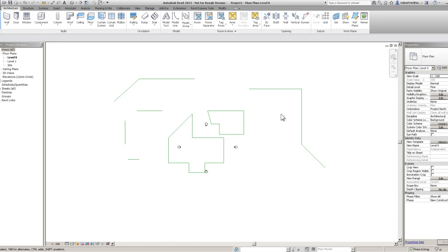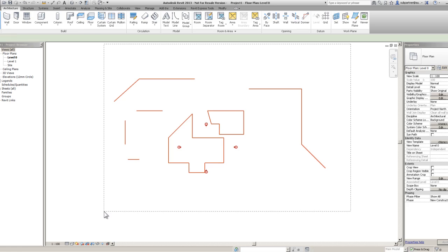This time I'm going to go from right to left, and again I'm going to left click and hold and drag my mouse. You see this time it looks like a slightly different window, again similar to AutoCAD. Remember, after showing you all this stuff, AutoCAD is a swear word, but I will keep referring back to it just for now, to help you in this transitional phase. As you can see, the window is a dashed one, and as you've probably guessed, the dashed one will highlight or soft select anything that it touches. It's more aggressive, it's quite nice. I quite often do it when I want to select everything. I just go bang, drag it over there, there we go.